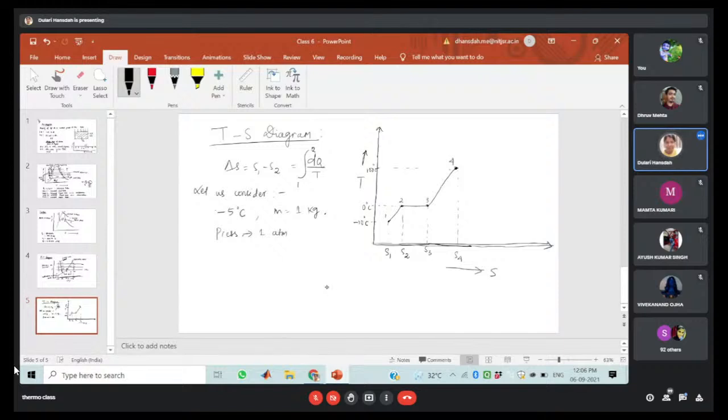So now here, at constant temperature, your phase change happens, right? Phase change means here liquid will convert into the vapor. In between, in this case, there will be the liquid vapor mixture. So here you get point 5. Here your temperature is 100 degrees Celsius, constant temperature and constant pressure. So suppose again we are heating that vapor. Let us take the heating temperature as 250 degrees Celsius.